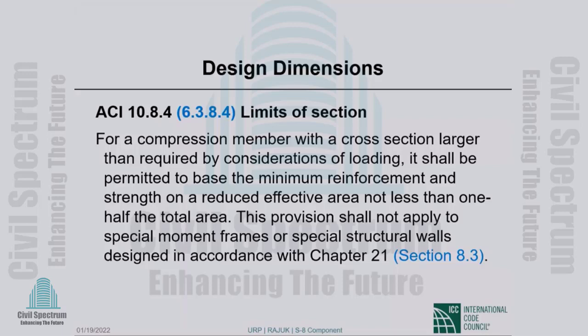I don't mean the completed structure with glass and marble and bathrooms, no, but the structure itself, the skeleton before other things go in. The cost of the structure, half of that cost is in the formwork. So you have to keep formwork simple.